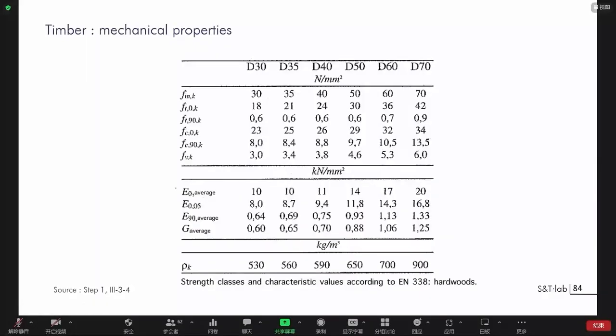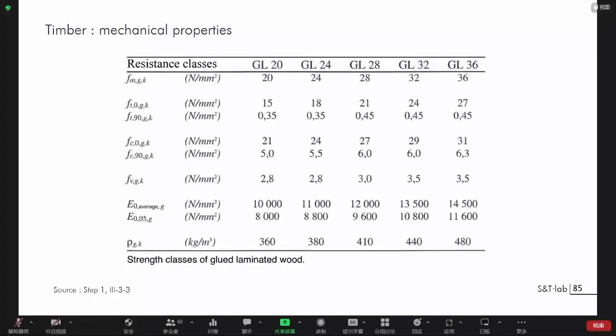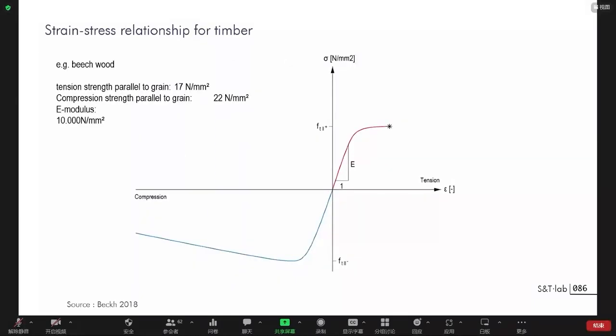I was mentioning also that of course the level of resistance is higher for hardwood, and also in between with glulam, since glulam is just extracting what would be the knots of timber, a whole singularity of defect, producing a better material from material that is not that efficient at the very beginning. What has to be mentioned is that timber in compression, in blue, has plastic behavior, but almost a fragile behavior in red on the curves.